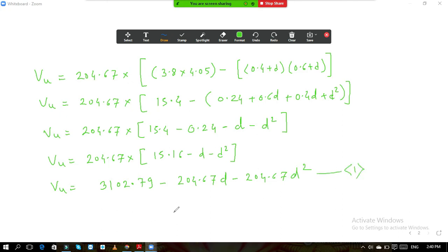ओके, मगाशी आपलं काय झालं होतं, लक्षात आलं का तुमच्या? असं एक्झाम मध्ये होऊ शकते. We have taken this quantity in kilonewton per meter square stress, and we have taken all these dimensions in mm. 400, 600, those are in mm. Actually we should take the same unit. आणि आपण काय झालं, हे mm मध्ये घेतलं आणि हे मीटर मध्ये घेतलं, त्याच्यामुळे त्या मोठ्या क्वांटिटीज येत होत्या सगळ्या 10⁻⁹, 10⁶. ओके, सो डू द करेक्शन. So in this way, now you can see how maintaining the uniformity of units is so much important.